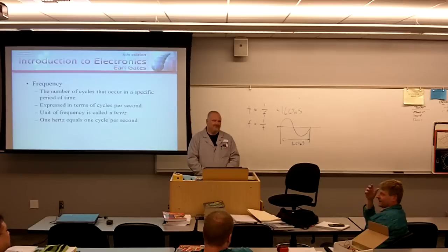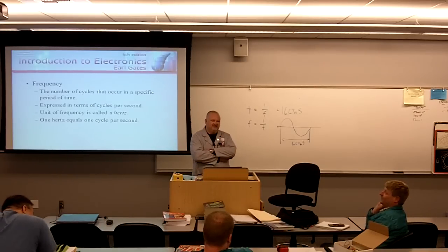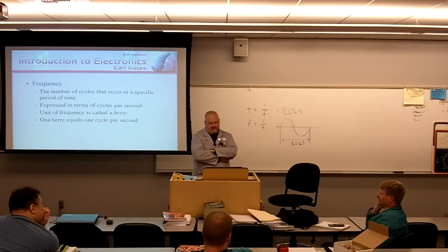Strobe effect, yeah. It would make the blade look standing still. There were lots of accidents that happened, and so they changed lighting to 2-phase. Apparently there was a big problem for the old people who worked in the wood fabrication industry many years ago. It does make a difference.